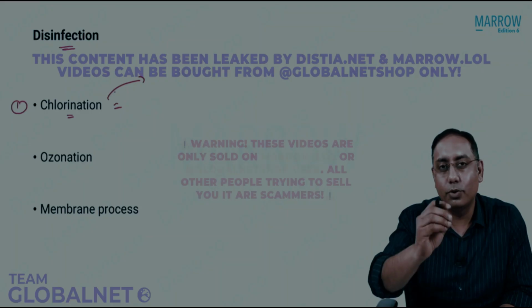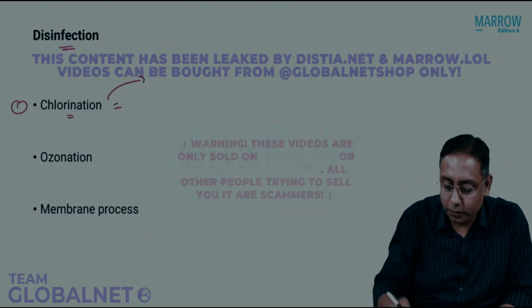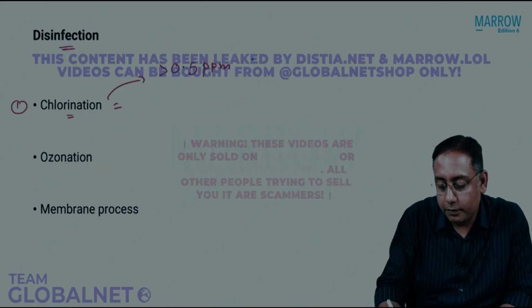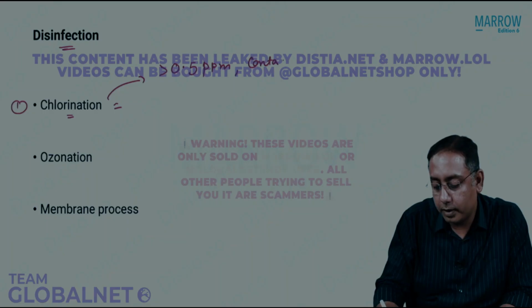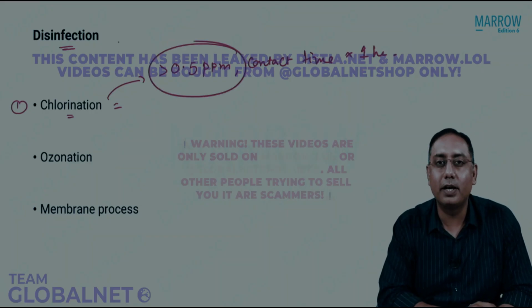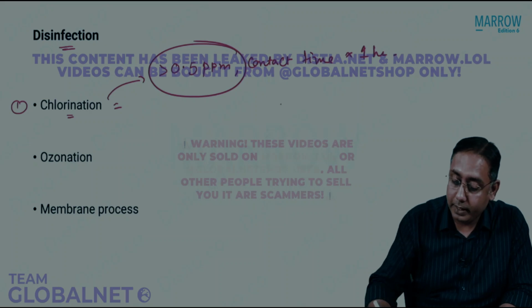You would like to use chlorine gas. And the chlorine gas should give you a level of chlorine which should be more than 0.5 parts per million after a contact time of 1 hour. So please note that the criteria for chlorination at a larger scale is 0.5 parts per million, in case there are impending outbreaks.